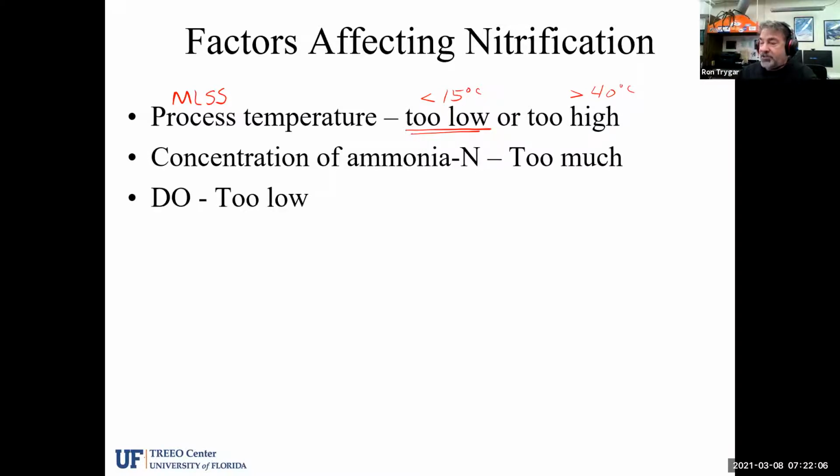So the dissolved oxygen could be driven down because of the excessive amount of ammonia coming in and the burden that places on the available oxygen in the mixed liquor. We call that dissolved oxygen. If the dissolved oxygen drops too low, or it's already too low, we may not have enough oxygen present for the bacteria to do their job.